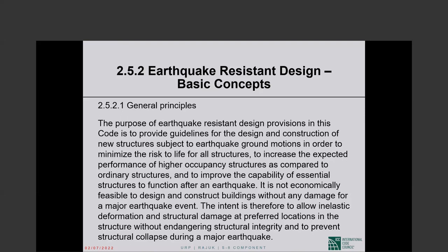We are not designing for elastic response to the design earthquake. We deliberately allow inelastic deformations at selected locations under the design earthquake, but we have to make sure that the inelastic deformations are within inelastic deformation capacities so that we do not have collapse. We do not have problems with structural integrity.